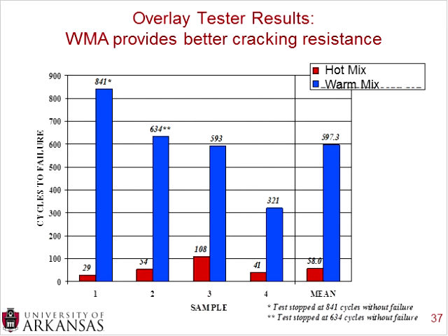But even with that variability taken into account, if they had done a little statistical analysis on this, I think that the 58 and the 600 are statistically different. So you see a statistical increase on the number of cycles of failure, which is a prediction of then what happens in the field.